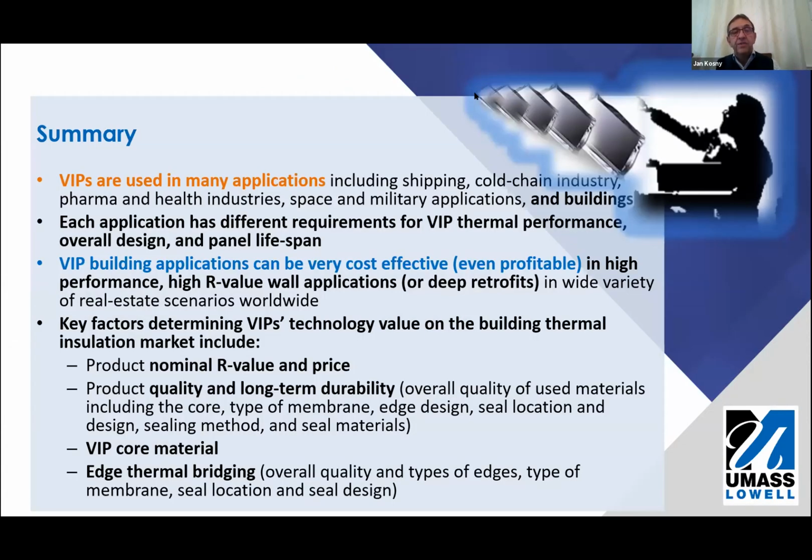That's the end of my presentation. In the summary, I would like to say that we always have to remember that vacuum panels have a lot of different applications, and each application comes with specific recommendations and requirements for those panels, which come with special designs. So panels are not identical. The most critical factors in market value are the nominal R value of the panel and price. The second factor is panel durability, which is strongly related to the core material and the design of the seals and membrane materials.